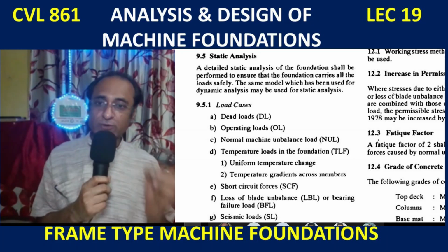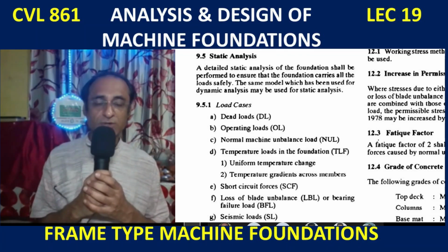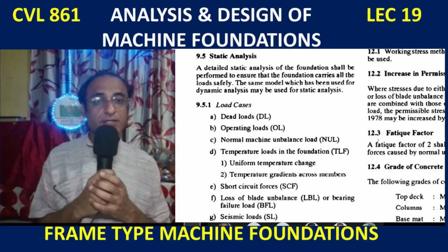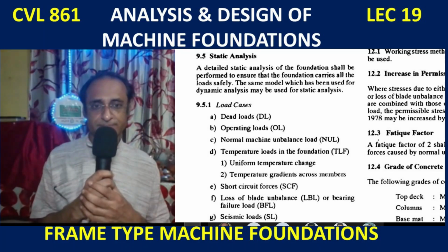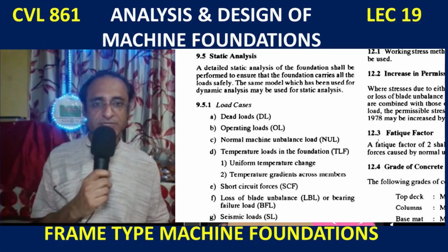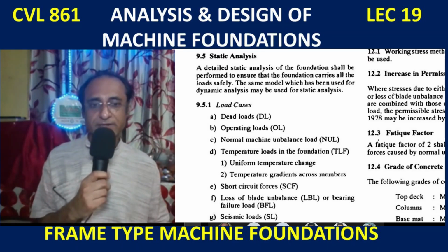So when and why do we need the dynamic analysis? Anyone can guess? The answer is that static analysis is fine for the load combinations, but dynamic analysis is necessary for the frequency check and for the amplitude check, because the amplitude check has to be done for the dynamic, operating condition, and also we need to determine the natural frequency of the foundation. So for that only we do the dynamic analysis.